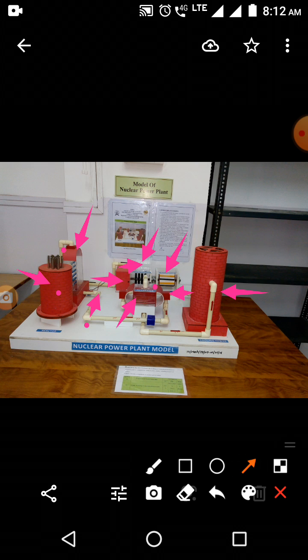As the steam loses heat, its temperature reduces and it changes phase from gaseous to liquid. When the temperature comes down from above 100 degrees to 60-70 or 50 degrees, this hot water goes this way, and again goes to the heat exchanger.